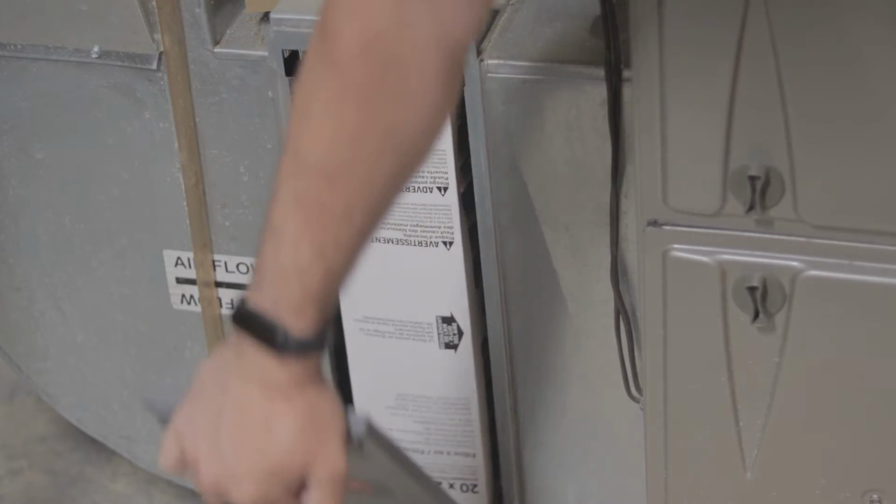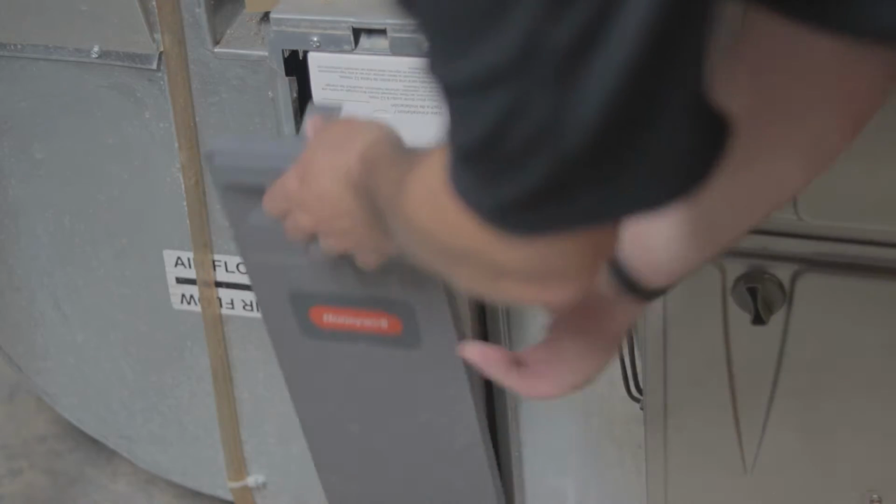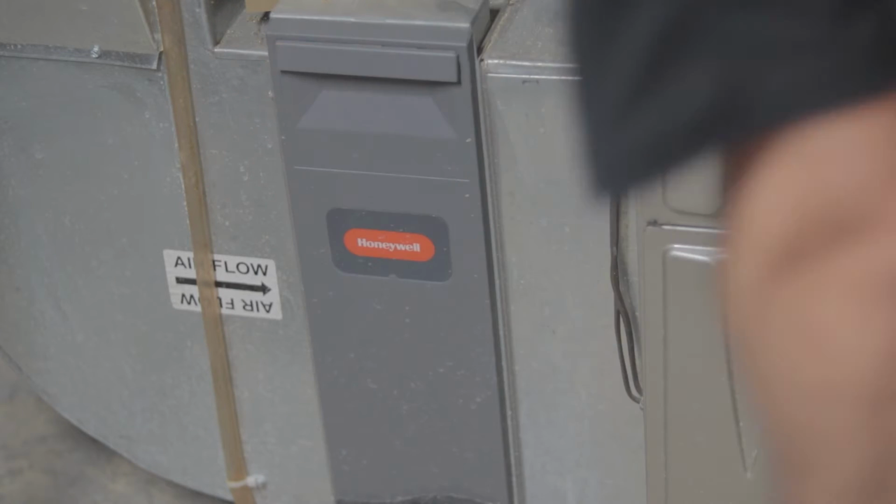So what you need to do is ask yourself, when's the last time you replaced your air filter? Each manufacturer of your air conditioner will tell you how often you need to replace your air filter. Most commonly, it's either monthly or quarterly. Some air filters that are the bag style can go up to a year, but make sure that you have been changing them. If you haven't changed it in the last quarter or so, go ahead and change it. It's a cheap fix.